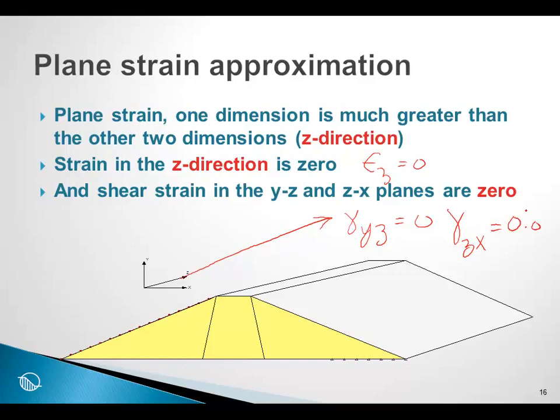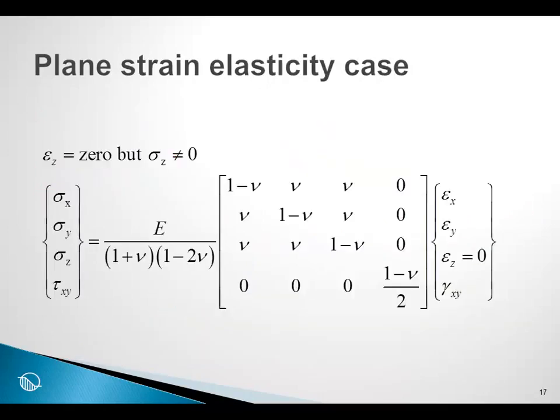So for a plane strain analysis, we are left with this constitutive relationship written in matrix notation, in terms of stress equal to strain. When we write it in matrix notation, the first row of this matrix multiplied times this vector gives us sigma x. The second row times this vector gives us the stress in the y direction, and so forth.